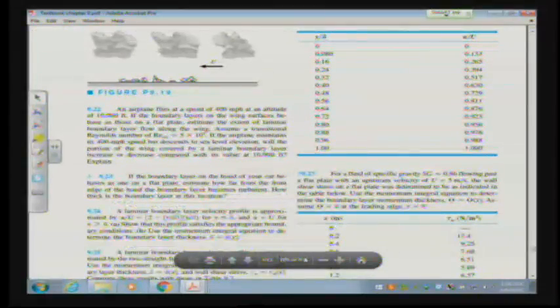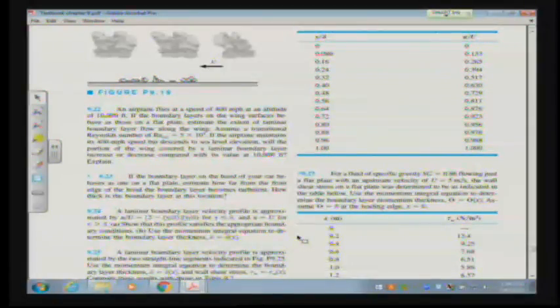All right, so 9.24. We have a laminar boundary layer velocity profile that looks like this. u over U is this function for y less than or equal to del, just meaning that we're between the boundaries of the plate, and u is equal to U for y greater than del. So at some point, we're going to expand beyond del, and we have a different velocity profile, don't we? It's just going to be constant. Show that this profile satisfies the appropriate boundary conditions.